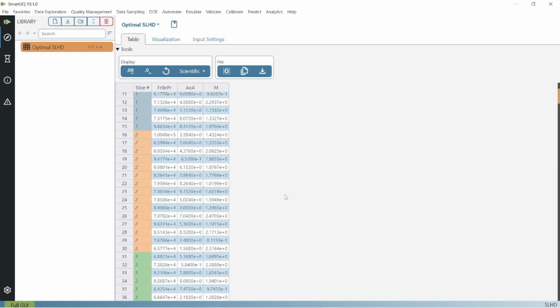So you may have a question as to why I gave 15 runs per slice. So the reason is initially the recommended runs is 30 for my case. So if it is not accurate enough, I don't want to do another 30 simulations. I would like to do fewer simulations and add it to improve the accuracy. So this is the reason I selected 15 runs per slice.